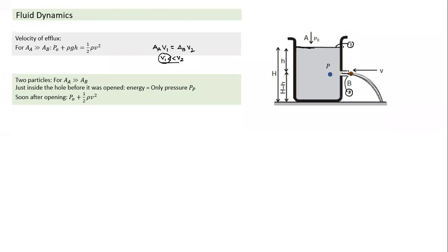So if I write here, let me write the equation here. Pressure at point 1 is P naught. That's what he has written. The kinetic term, 1 by 2 rho v square, we have ignored here. And if I take the nozzle as the reference level, then rho gh, the height above the nozzle level, becomes equal to, sorry, I missed this term P naught here. This P naught has to be added here. So this is equal to 1 by 2 rho v square plus P naught.